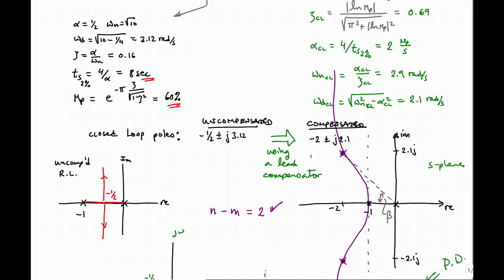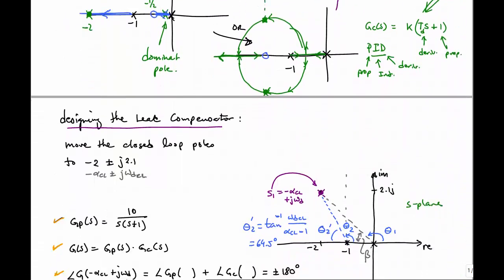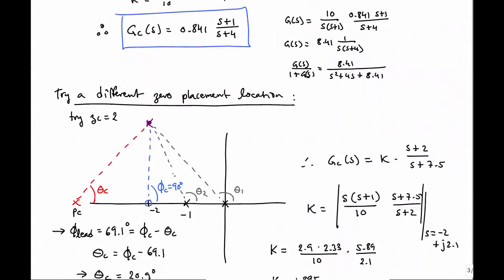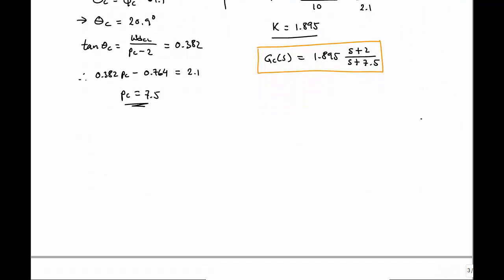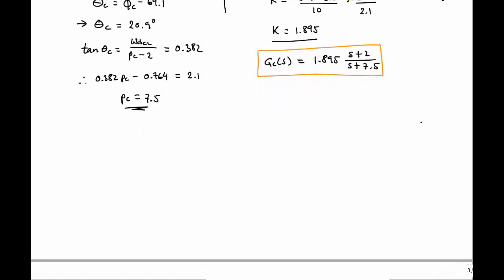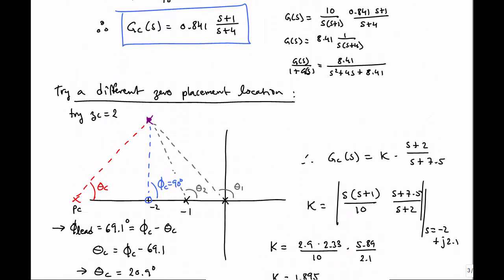And so it would seem that we should have an overshoot of 5%, but we don't. And let me try to give a little insight on this. It's a little bit of unfortunate news. It means that there's some trial and error needed here. You could develop more analytical tools and procedures to compensate for this, but at some point you decide just to iterate. So let's consider our first system here.